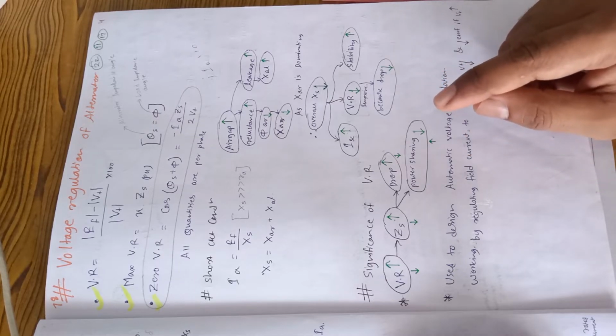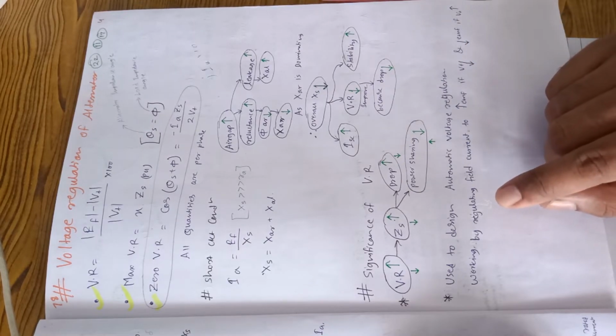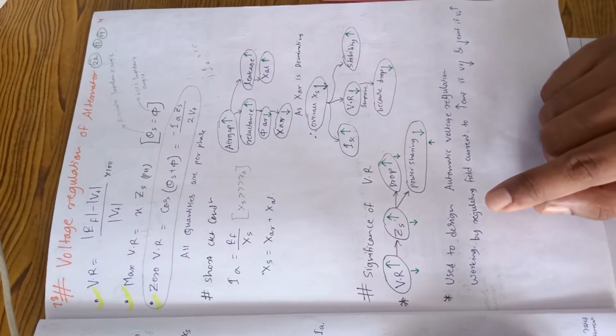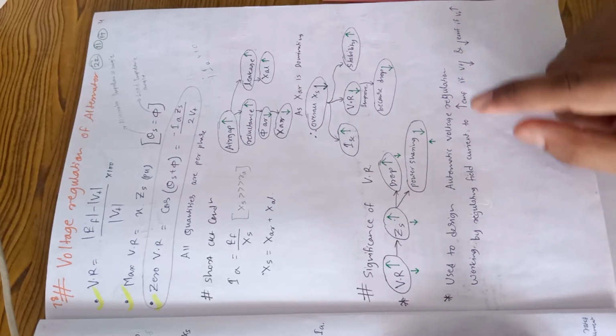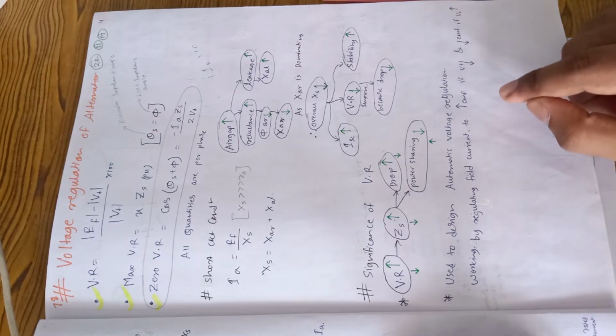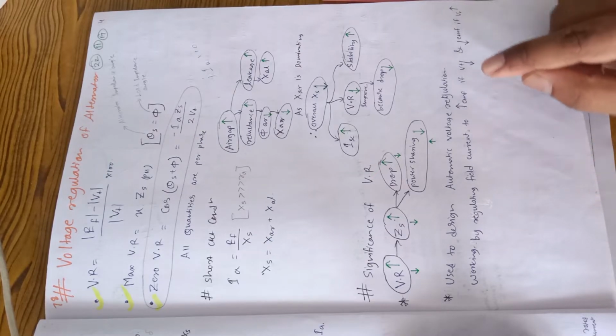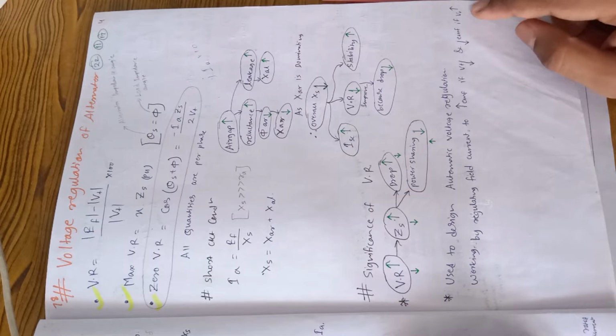The most important importance of voltage regulation is that it helps us to design an automatic voltage regulator that works by regulating the field current to increase EMF if terminal voltage is decreased, and to decrease EMF if terminal voltage is increased.